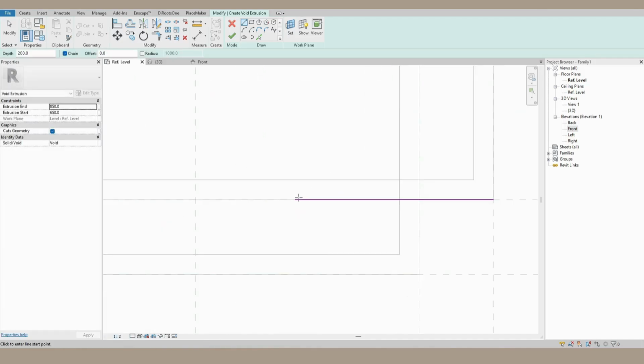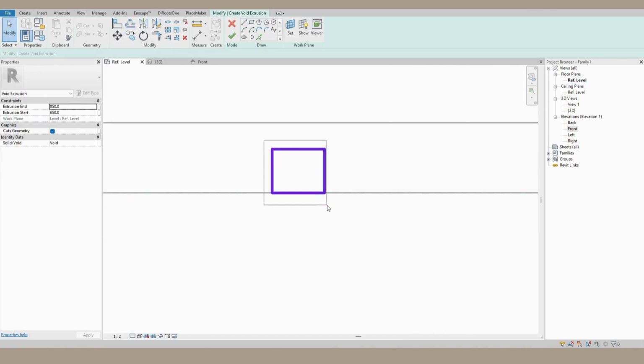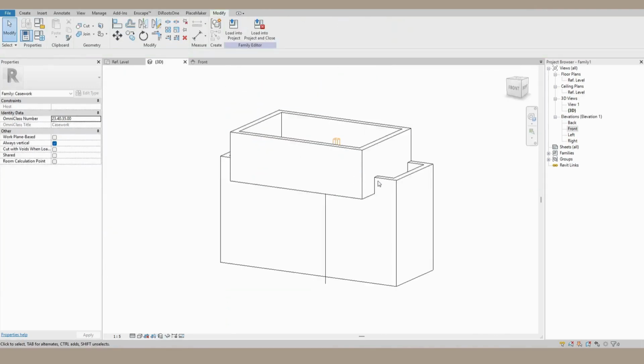For instance, it's just a door. I like to leave a bit of a shadow gap. If it's a finger grip, probably 30 mils deep is enough for you to put your finger into that and grip it out. However, this might be a bit too deep if you are trying to show this only for graphical reasons. For example, in a 3D render, in a model, you need to gauge what it looks like. However, 30 I would say is a good finger grip. So don't let it cut through all the way.